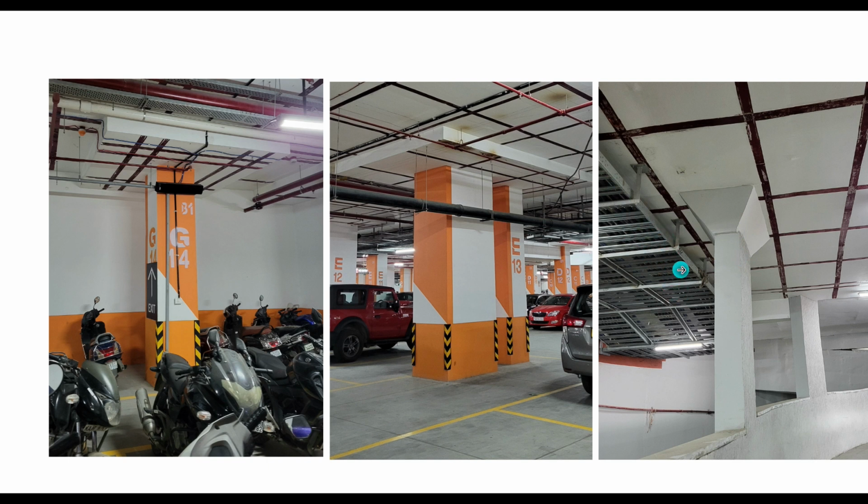So there is a constraint over here. To avoid the constraint, they cannot give a drop over there. So what they have given is a column capital instead. And in the back end you can see here we have a column, but there is no capital, there is nothing over there. There is basically a flat plate system in the back end.